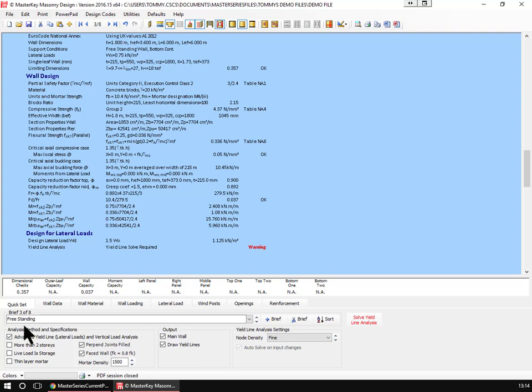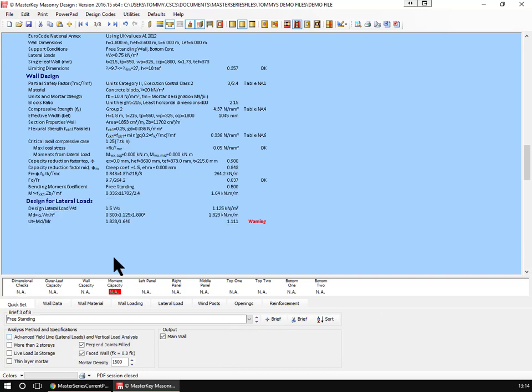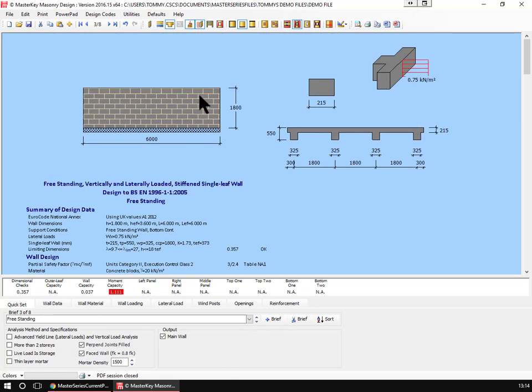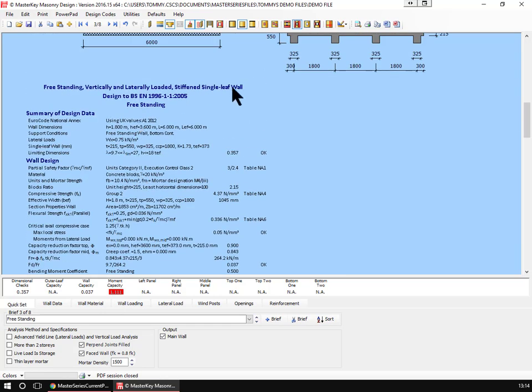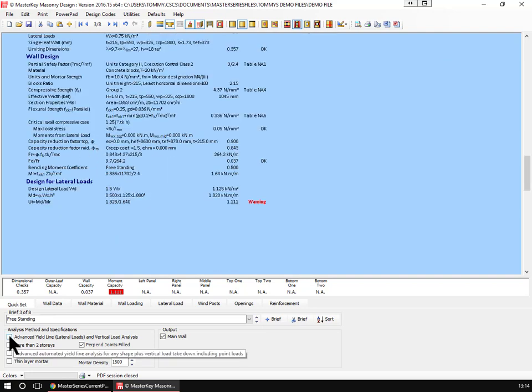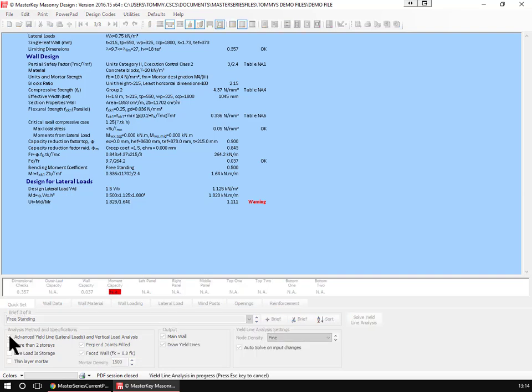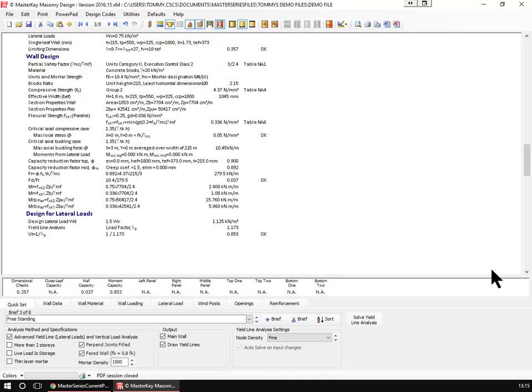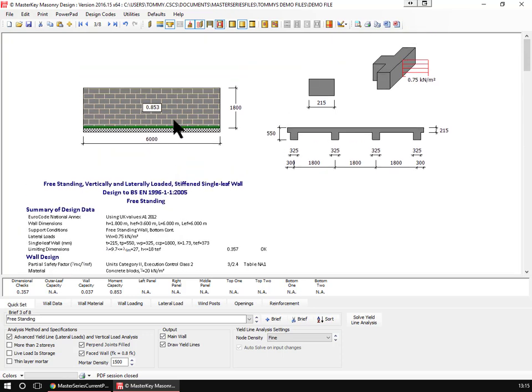Now, I can turn off the yield line analysis and show that the wall under the old-fashioned spread is failing by 11%. So using the old-fashioned methods of little T-stubs here for these cantilevers, I can show it doesn't work. And at this stage I'm going to bring in this new yield line analysis, and we'll see that the yield line analysis is actually now showing that we've got a 15% reserve on our wall. So our wall is actually working.